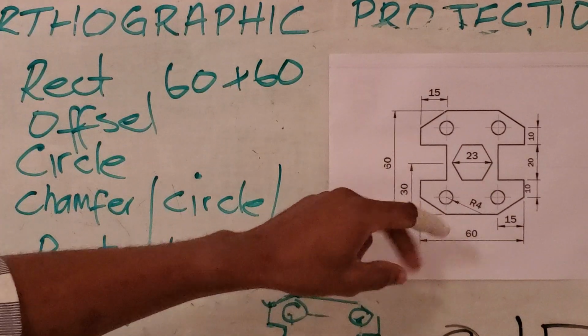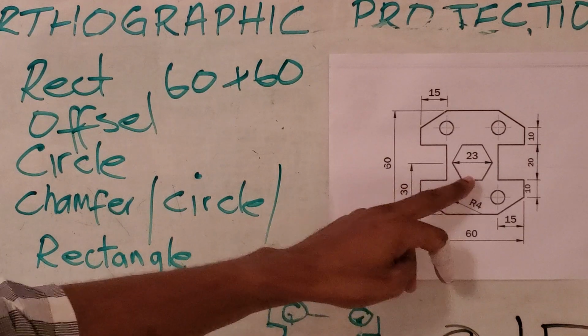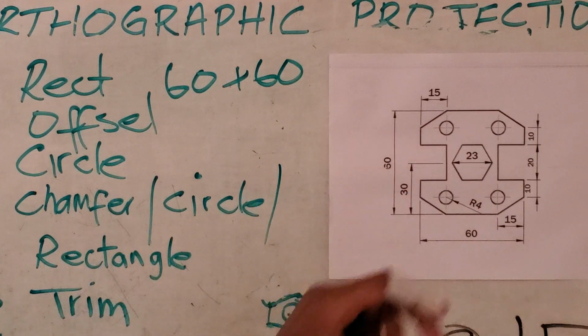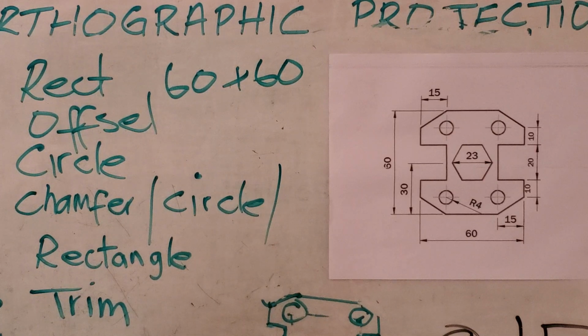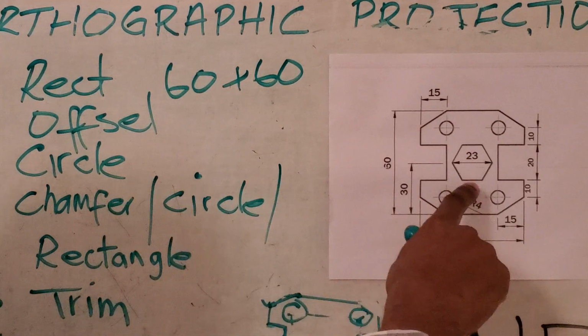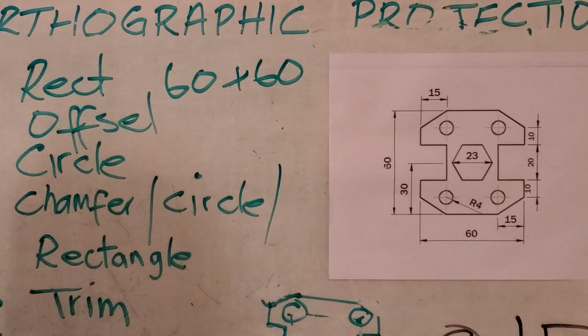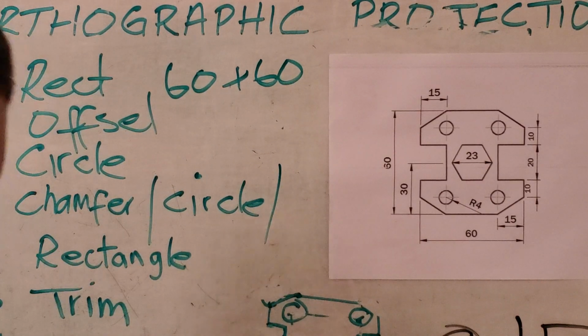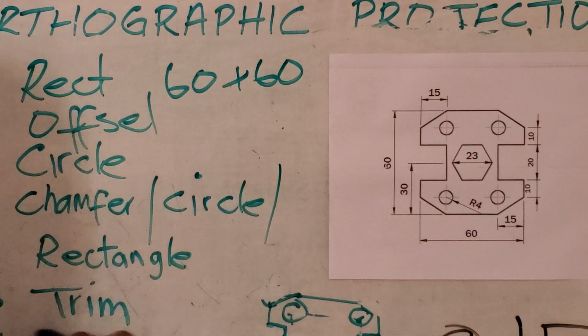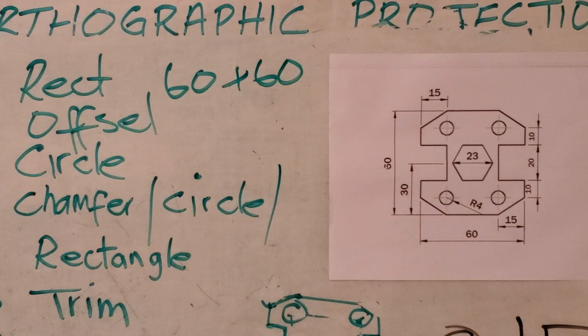Now, if when setting up you turn on center, this probably would pop up. However, if you haven't established your center, we need to establish a center for the polygon. For that we could use M2P, middle of 2 points. But before that, I would need to activate polygon.